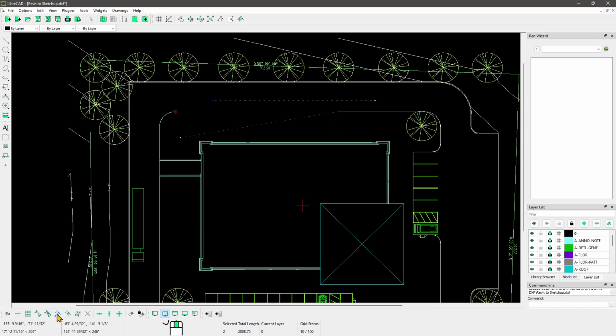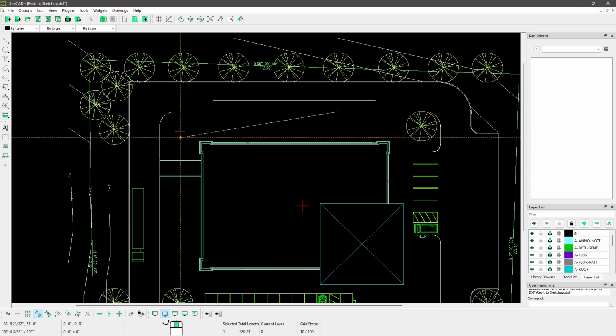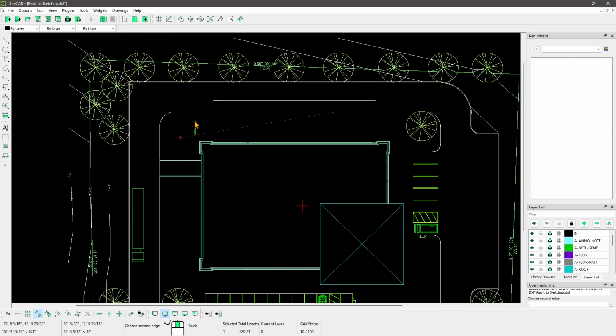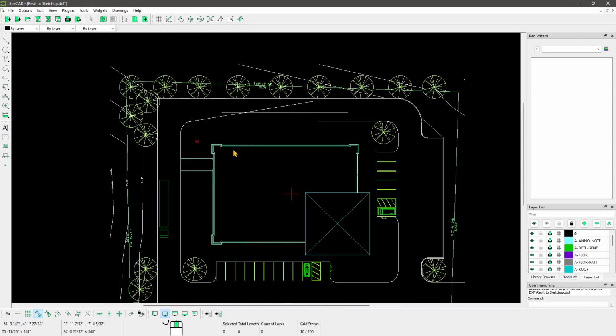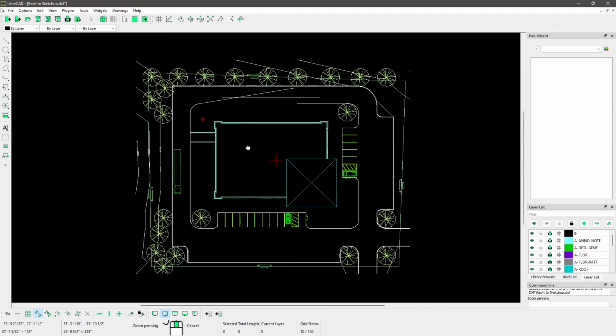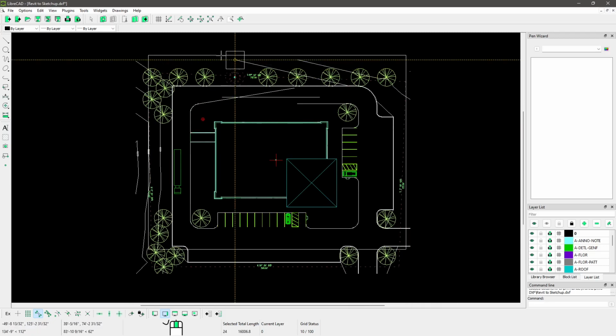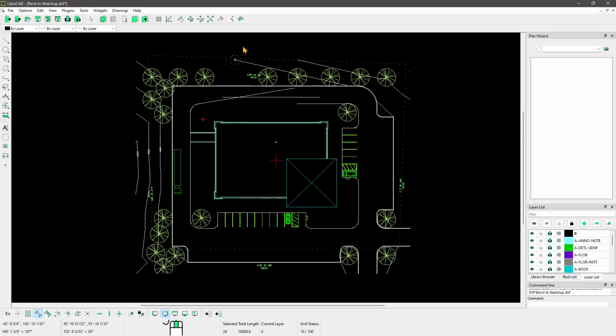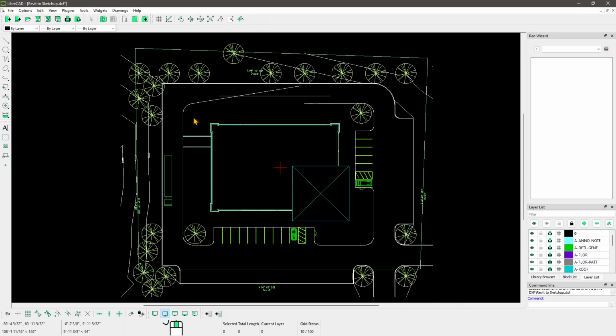And of course, I can use the snaps. If I want to modify this line again, let me just select it with the left mouse, click and drag, and you can see I can now move this line. There you go, and snap it right there again. So I can use the lines that I already have. I can edit this drawing. I can select parts of the drawing. This is a block probably. So when I move it, it's gonna move all together here. And I can continue to draw on top of this.